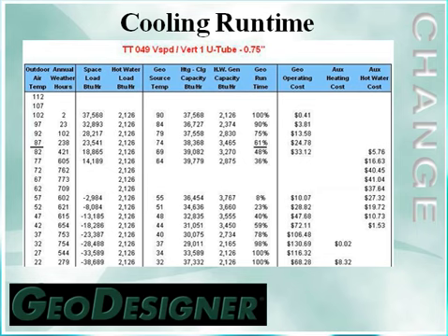In the bin analysis tab, we can look at information over here. On the far left side of this screen are our outdoor air temperatures and how many annual hours per year at that condition, and then towards the middle of the screen, our geo runtime in cooling as a percentage. What we'd like to see is that at about 85-degree outdoor air temperature, we're at 50% runtime. That's enough run time for the machine to pull moisture out of the air and do good dehumidification so we have a comfortable, cool home.